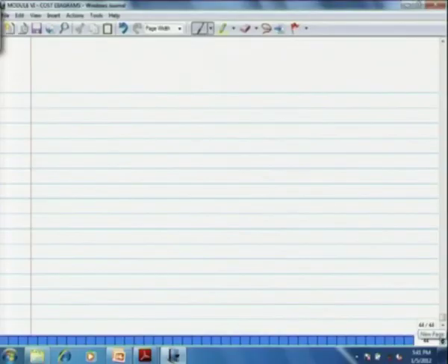In the previous lecture, we had the toluene feed fresh to recycle in the ratio 3:1. So, we split all the cost of the columns in the ratio 3:1. Here it is different. So, we have to first allocate the heat duties in proportion of molar flow rates and thereafter distribute the cost. So, that we do now.